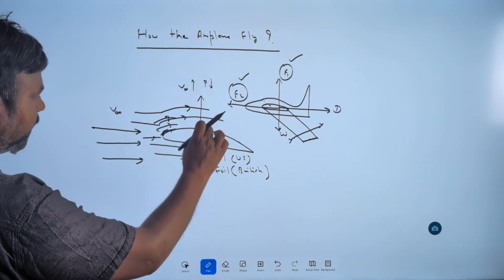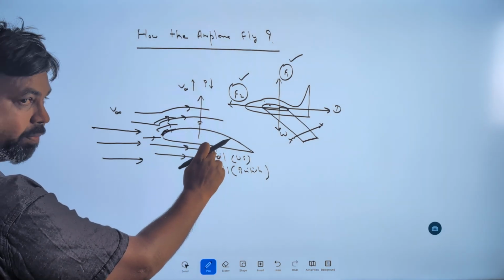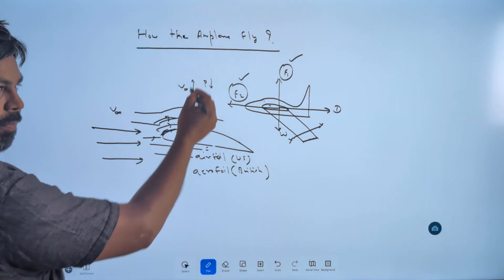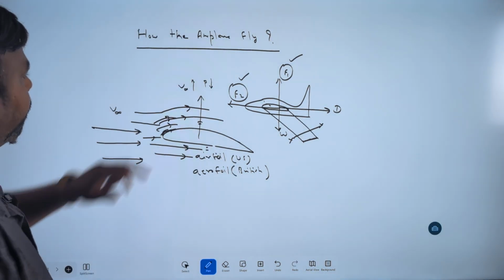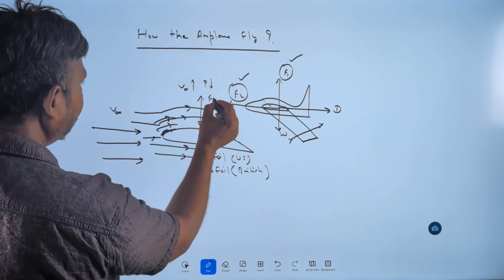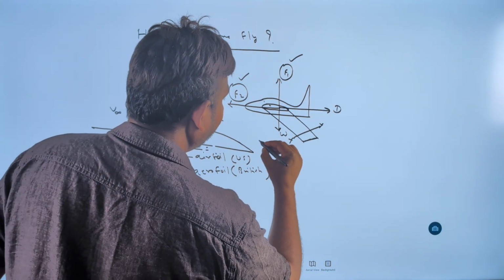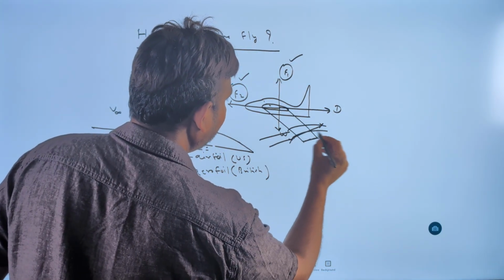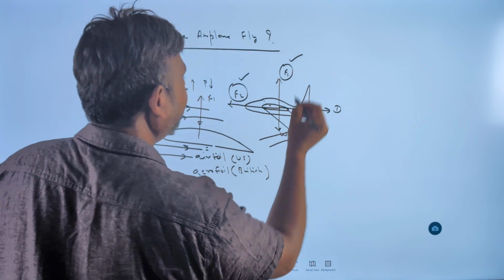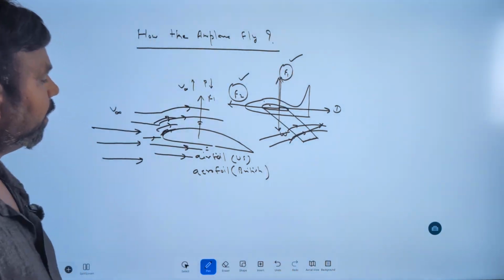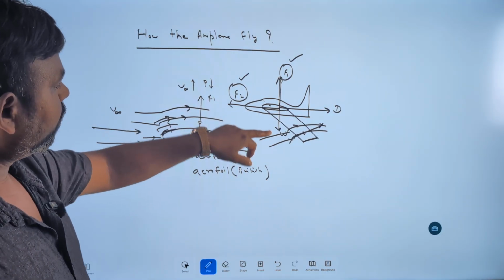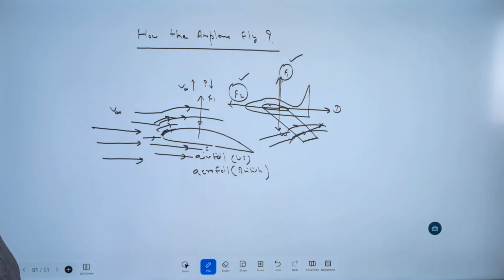So there is a pressure difference now between the upper and lower surface, then there will be a pressure force from the higher pressure to the lower pressure. Now we got this force F1 here. Because the flow is coming and getting accelerated, these wings will generate a force that I am taking as F1, and that is at least equal to W, the weight of the aircraft.